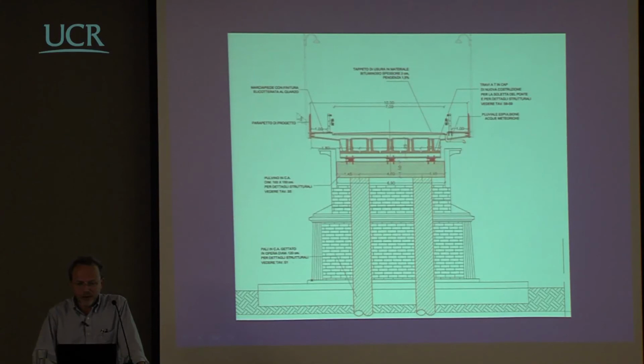That's the reason why there are 3 here, and we used 3 on the piers and 2 at the abutments, just to adapt the design to the available devices. But starting from the point that, for several reasons, one of them this possible gap here, we were going to design for a relative displacement of 200 millimeters. So we started from the 200 millimeters, and believe me, there is no other way to design the isolation system.